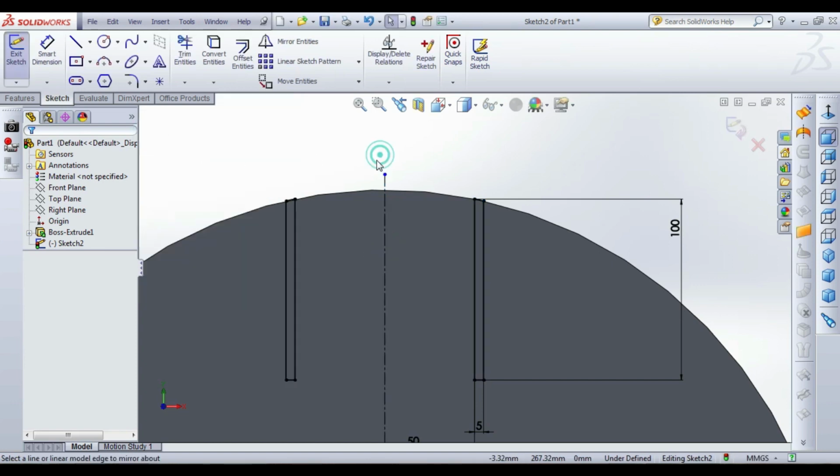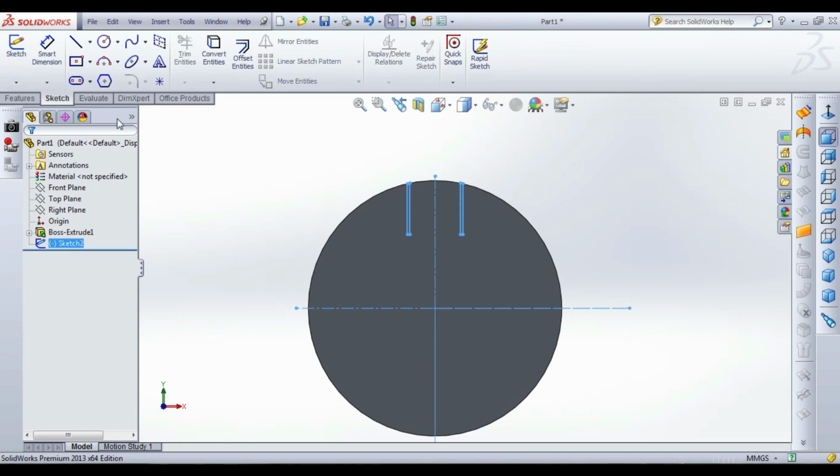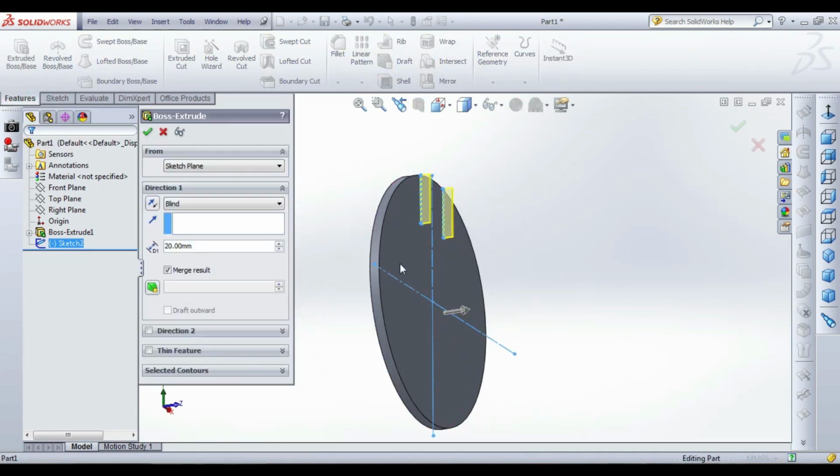Okay, now the engine block is completed. The single side of the engine block is completed. Going to extrude based on the top surface. We can extrude 40. Now above is a single side blind; double side extrusion is also possible. The extrusion length is 60.